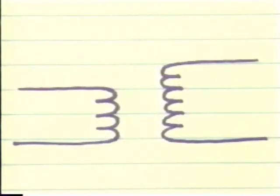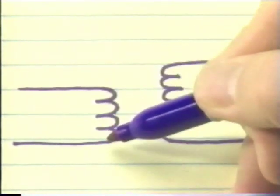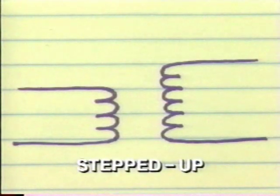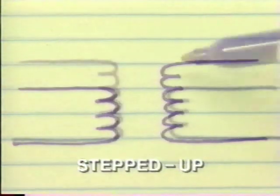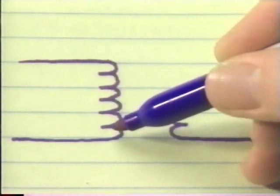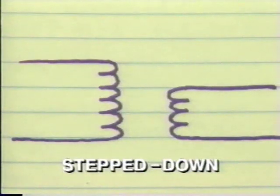From this example, you can see that if there are more turns in the secondary than the primary, then the secondary voltage will be greater or will be stepped up. On the other hand, if the number of turns in the secondary is less than that of the primary, then the voltage will be smaller or stepped down.